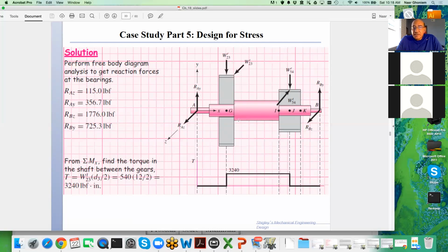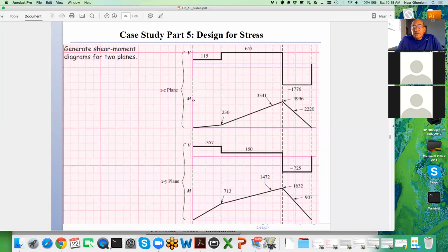So set this on the side, and then we go ahead and do a shear force diagram for the XZ plane, as you can see here, from the forces. And these are all point forces, so it's a very nice, easy system. There's no distributed force, uniform or linear ramp or whatever. We just have point forces. So the shear force diagram is jump, constant, jump down, constant, until you hit zero again.